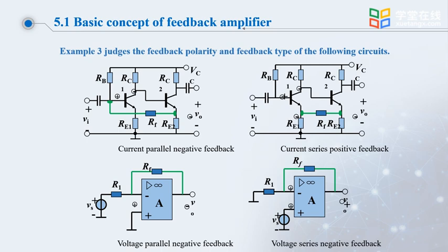That is, through the instantaneous polarity method, we can tell what this feedback element is feeding back. The point potential is an instantaneous drop. Since the net input signal equals VB minus VE, and the point E potential is now decreasing, VBE is going up.